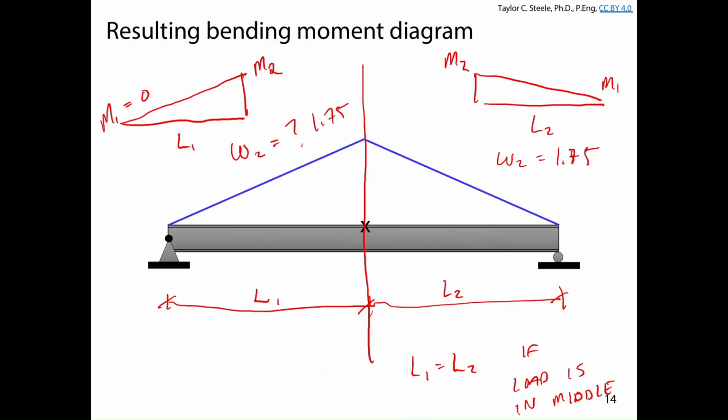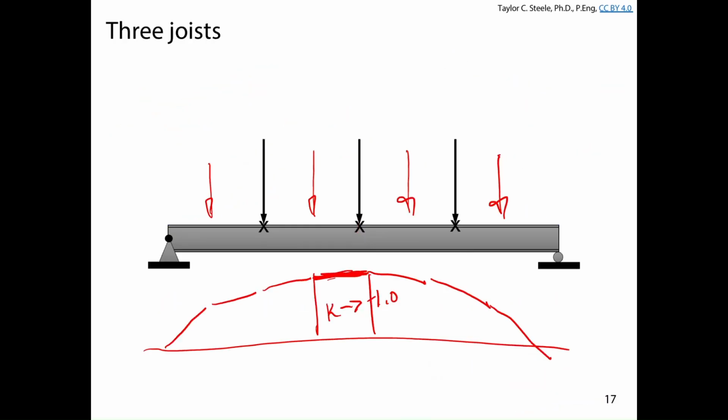The only exception is if you have one joist. That's an odd number, but we do get a significant increase in omega 2. So if a single joist loads your girder, you probably want to take advantage of omega 2 to increase Mu, but the more point loads you add, the less advantage you get, because the moment gradient gets closer to constant in the critical central region of the girder.